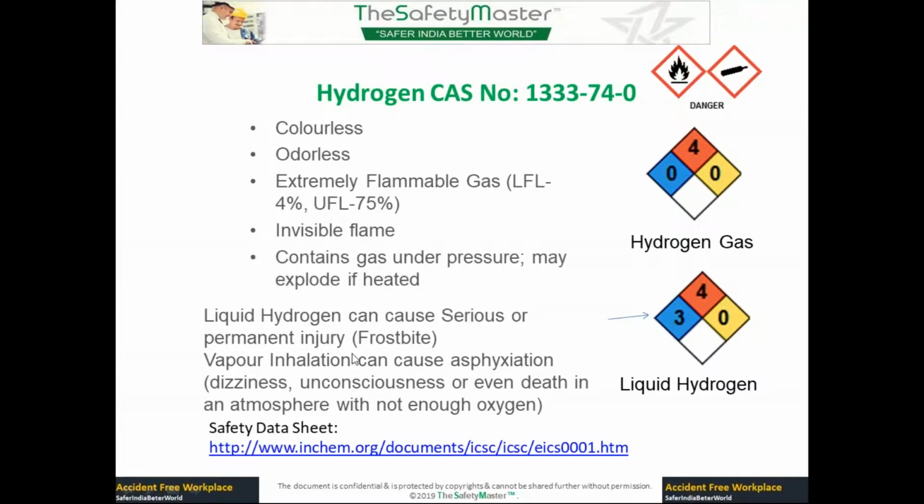And in case of liquid hydrogen, hydrogen is basically a colorless, odorless, extremely flammable gas, and the lower and upper flammability limits are 4% to 75%. Okay, and then it's an invisible flame, you cannot see it. Okay, I'll show you some videos. And it contains gas under pressure, may explode if heated.